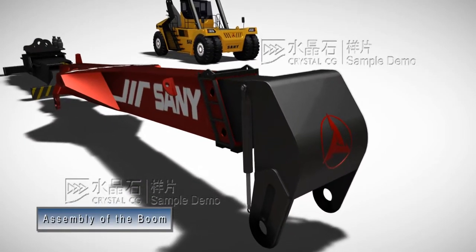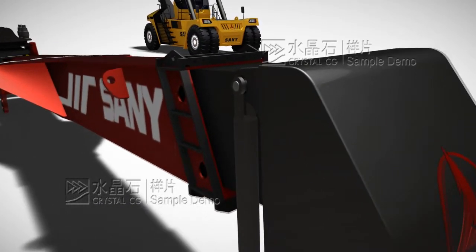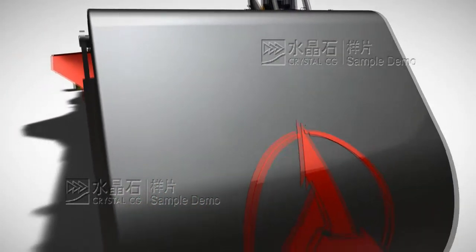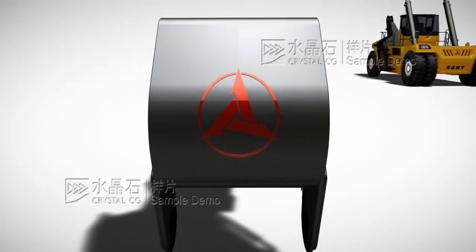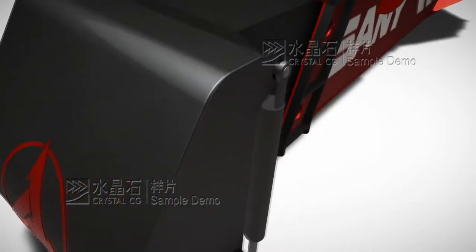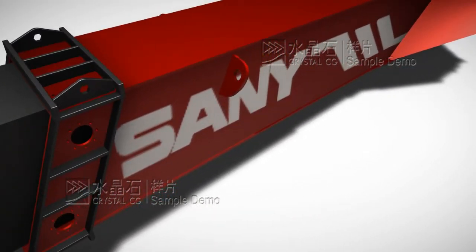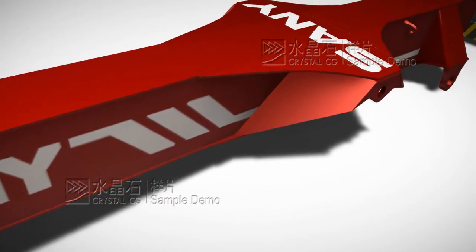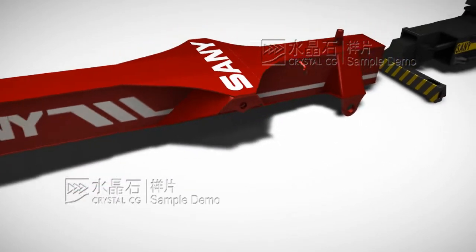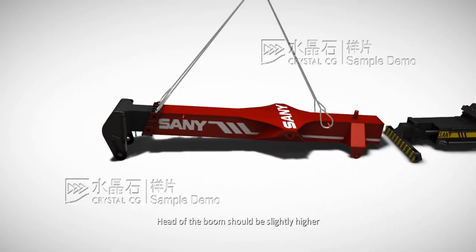Assembly of the boom. Check the connection between the swing cylinder and the boom. Hoist the boom with a crane of 50 tons.